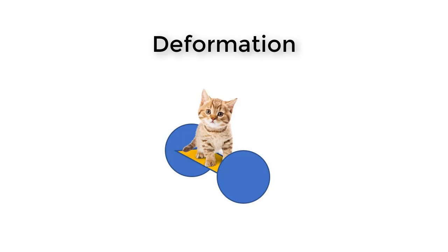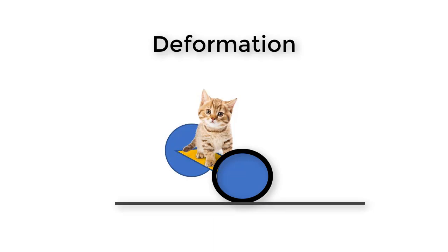There is at least a third source of energy loss in our system also: deformation. This is the energy loss that occurs because things in our system change shape or deform as they move. Suppose that these wheels have tires on them. That's likely necessary in order to achieve our no-slip condition. When the wheels contact the ground surface, both the tires and the ground will deform, that is, squish, dissipating some of the mechanical energy motion from our system, slowing down the rolling of the wheel.